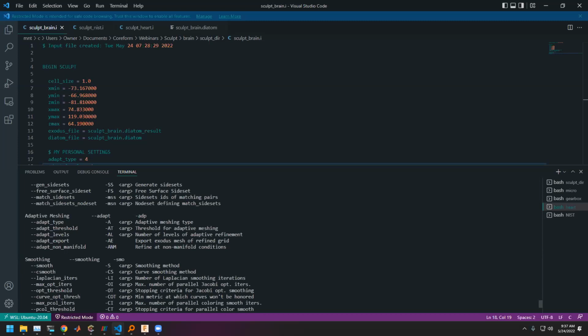If you've got tools from Autodesk, I think they've got an AM preprocessor. Materialise Magics has a good healing tool in their preprocessor. There's also Avizo and Volume Graphics, and I would use one of those tools to prepare the input geometry. And once you've got that, then come into Cubit.